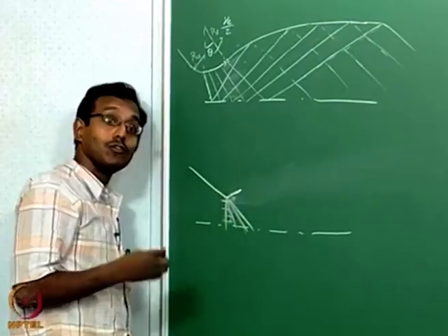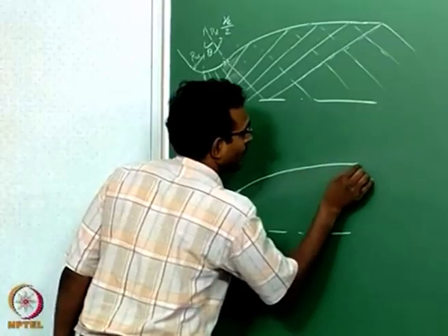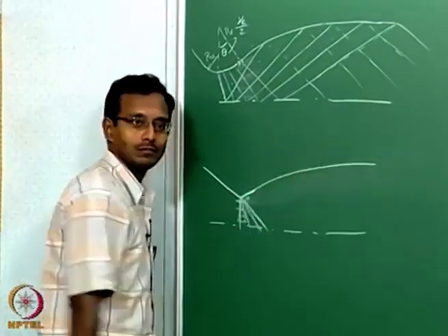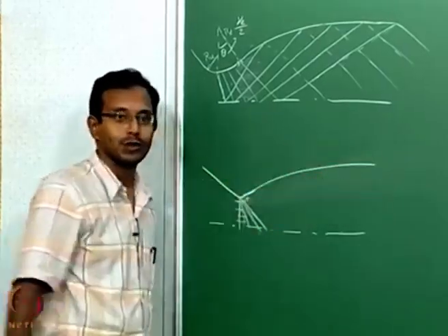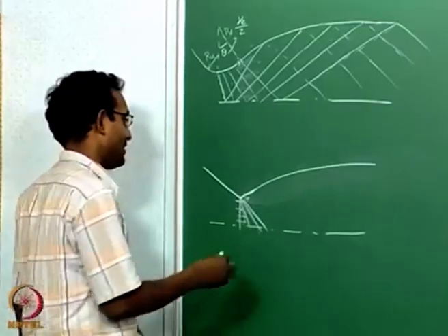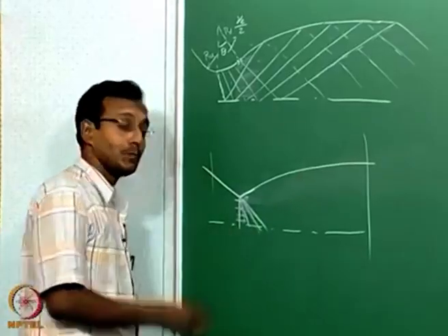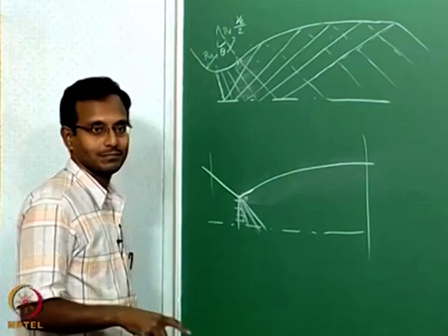Now if you look at your nozzle, it will just be a compression wall. This is all you will have, it will just be a compression wall. It is already expanded with point expansion and then a compressing wall, smooth compression wall. This is all it will be. This is what is given in all these standard textbooks as minimum length nozzle. This will be the minimum length nozzle that you can design with method of characteristics, okay.